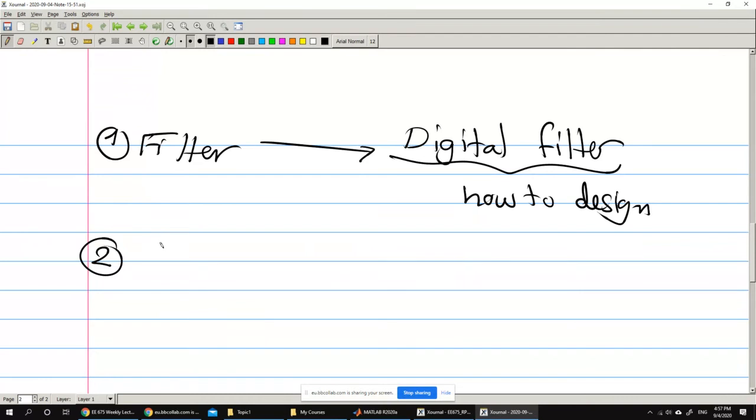If I wanted to design an amplifier, I would test this amplifier on a sinusoidal signal. Why do I do that? Because I know how the sinusoidal signal looks. If it gets amplified, I can detect the amplification from the amplitude. I can look at the sinusoidal signal and see if the amplifier did any modification or distortion to the signal, because I know how it looks. So this would lead us to something called simulation.